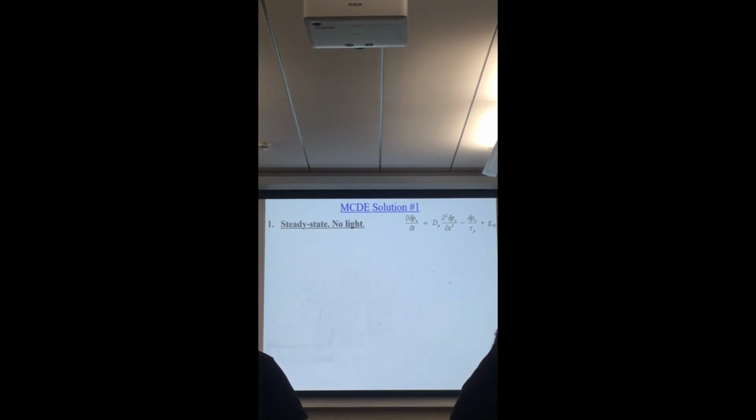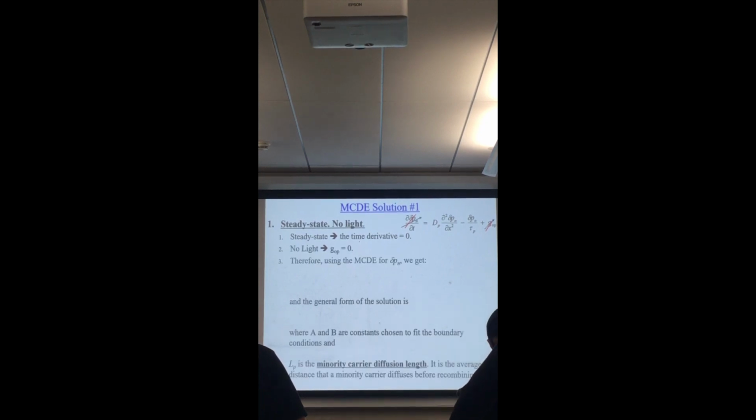So then we will see that this G sub OP is 0, and the first part, because of steady state, the time derivative will be 0. Then we can simplify this minority carrier diffusion equation. So this general equation will be like this.